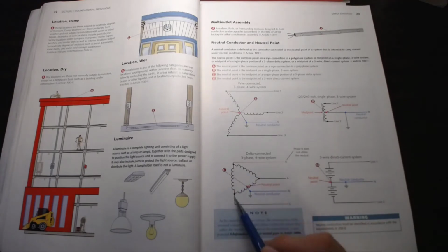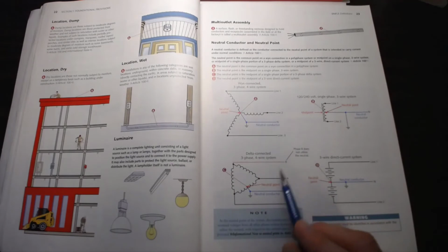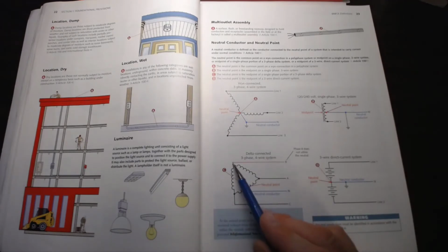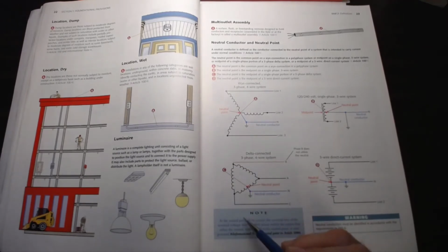And so we have a connection between all of these. So then when we connect a half a winding and a full winding, we end up getting 208 volts, which says B phase here is not utilizing the neutral, because you have 208 volts from here to here. So it's 120 plus half a winding gives you 208 volts. Two full windings, A to C, B to C goes through 2 whole windings here. That's going to give you 240 volts on a 120/240 center tap delta transformer.